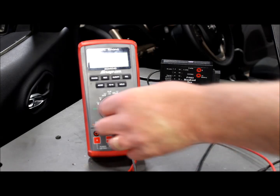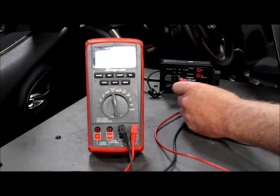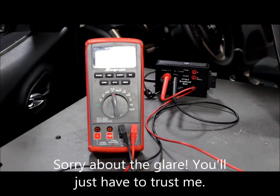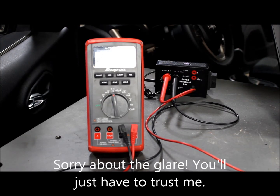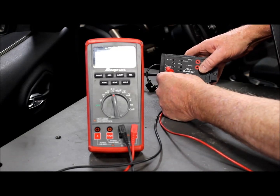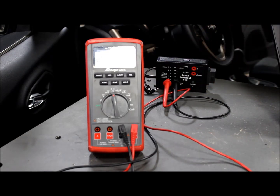I have the battery unhooked, set our meter to ohms, and I'm going to go from pins 6 and 14. And we have just over 58 ohms, pretty close. And now I'll go to pins 3 and 11. Pins 3 and 11, 61.7. So the resistance seems to be about what it's supposed to be.